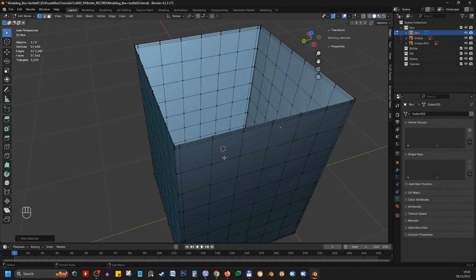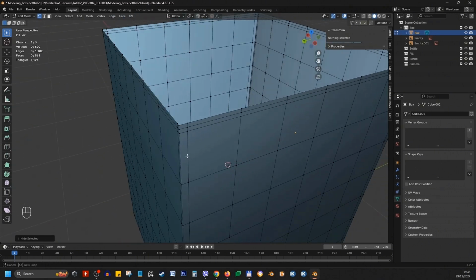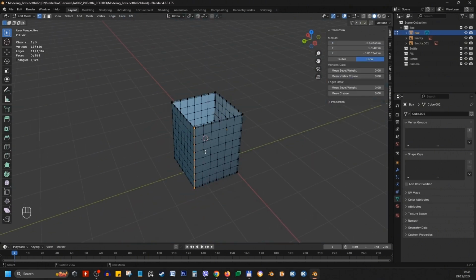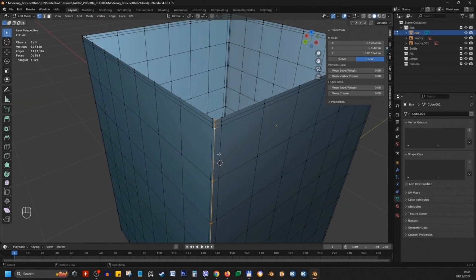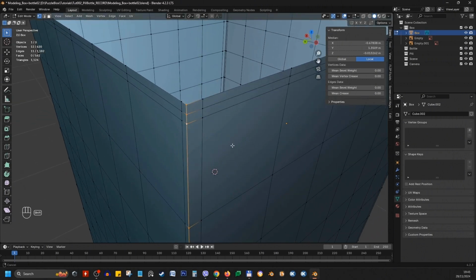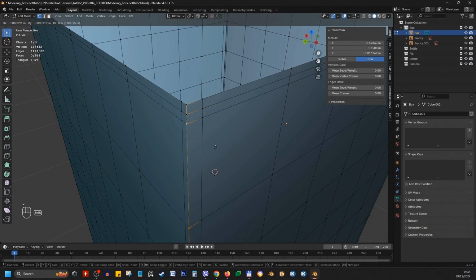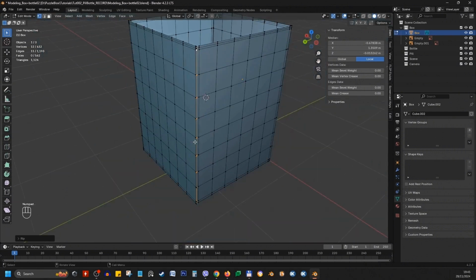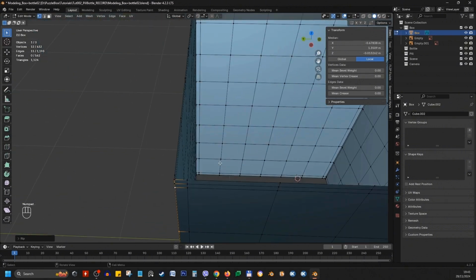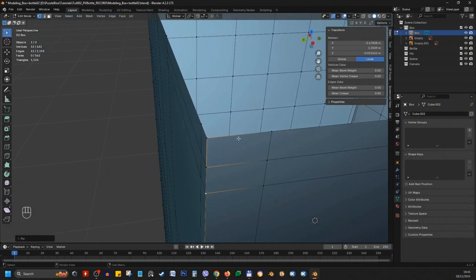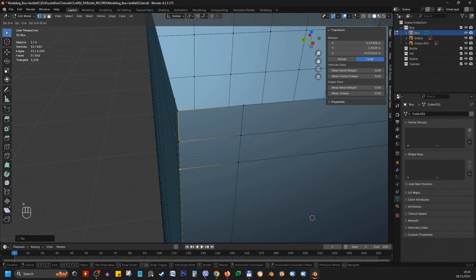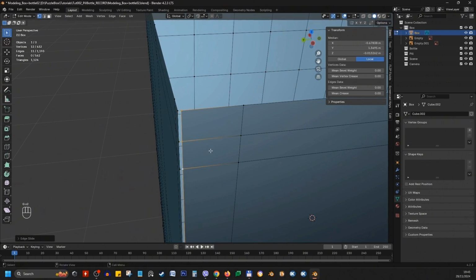Now we isolated just the middle body of our box. These boxes are not connected here. Hold down Shift Alt and select this edge here, V, to separate these two edges. Right click to snap it back into place, and tap double G to slide it back a little.